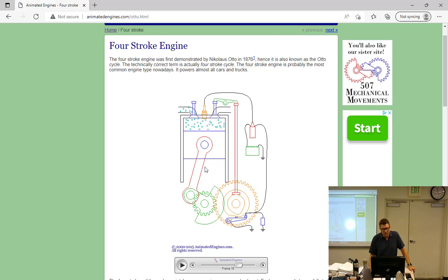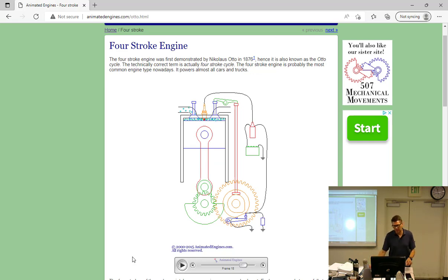So you need, for starting purposes, you must have the spark right there. That is called top dead center. And the reason why it's top dead center is, look at how that connecting rod, this is the connecting rod right here. Look how that connecting rod is 100% perfectly in line. Everything is this super straight line all the way up and down. That means it's top dead center.